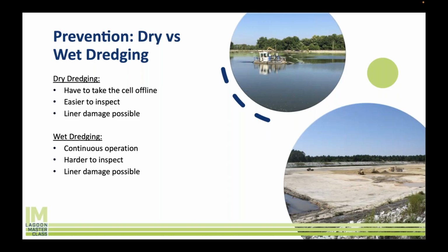And lagoons manage biosolids by storing them over a 20-year period, okay? I think this is great, personally. You don't have to touch this for 20 years. That's awesome. Some of these other plants, you've got to manage biosolids every day, and it's costly. But eventually, you've got to remove the biosolids. You've got to clean out your pond, and that's just part of the system.